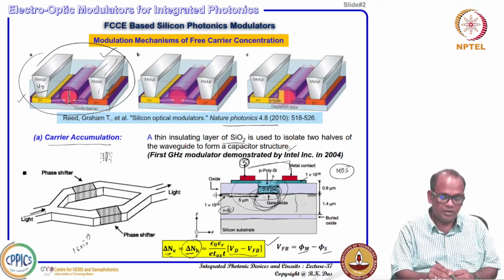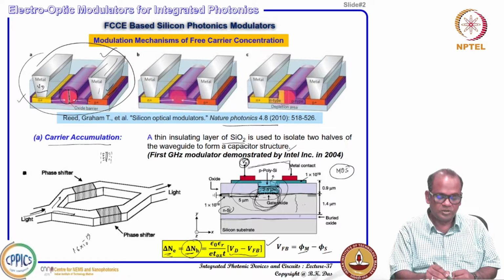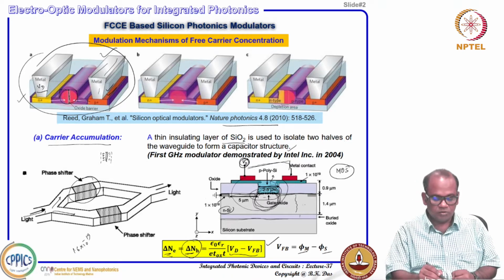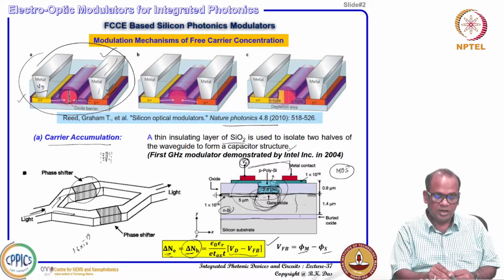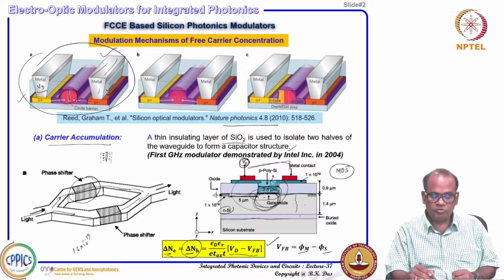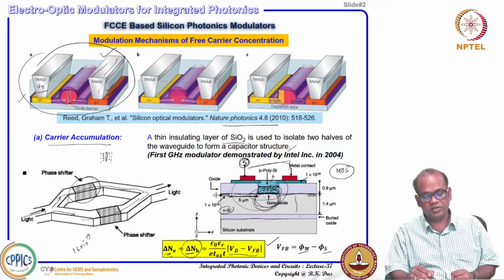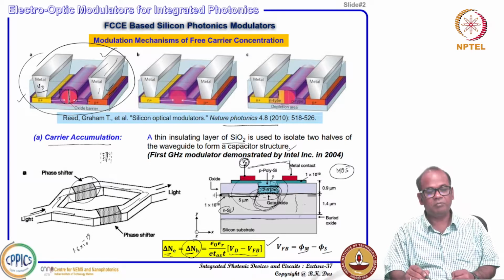Your light is guided here and split into 50% here and 50% here, and you can have a phase shifter on both sides, but you can utilize one of them, because there will be certain kinds of losses even in the absence of voltage in one of the arms. You can see that when the light propagates directly, they will be equally attenuated, so equal amplitude comes here and they will be constructively interfering. It will reproduce very constructive interference, and light will be there.